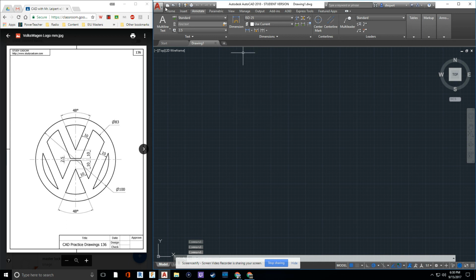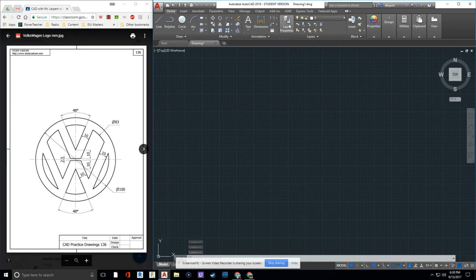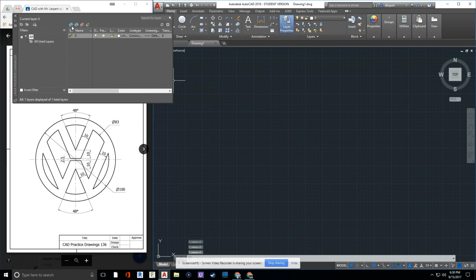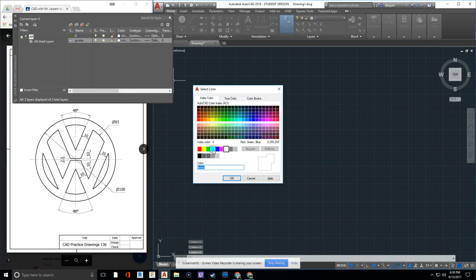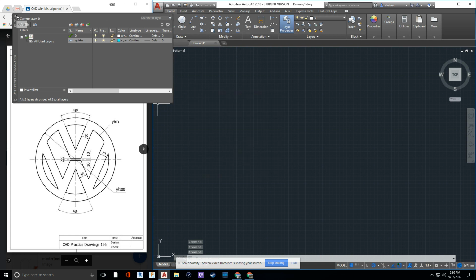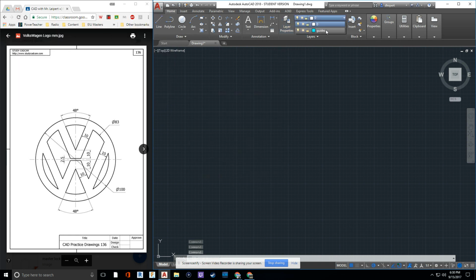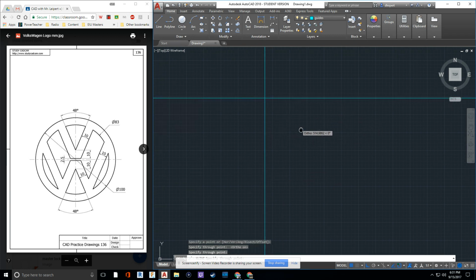And if you know my drawing style in AutoCAD, you know that I like to first go to layer properties and give myself a new layer that says guides or construction lines. And I changed the color to something that contrasts. Let's go with a teal in this video and exit out. Then I like to go to my guides and type in XL for construction line, hit enter and draw that line. Hit F8 to snap it nice and straight for orthographic, and we'll draw our cross line.